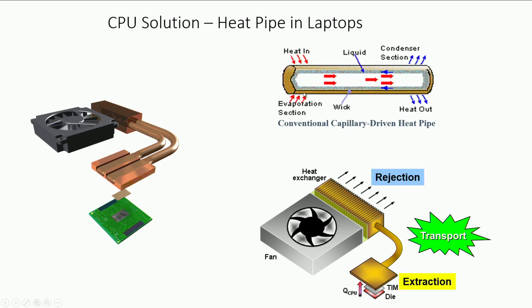wick to the evaporator section, and thus what you have is almost all the steps of a liquid pumped loop. You have water flowing over a heated surface where it changes phase. The vapor flows to a cold end where it is cooled and condensed, and the condensed liquid comes back due to capillary pumping action in the wick. Why does it come back? Capillary action. You have all lighted a diya, right?